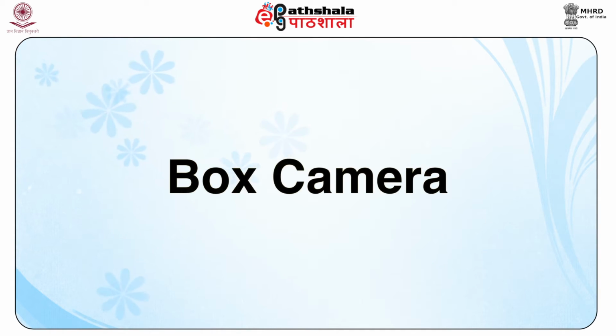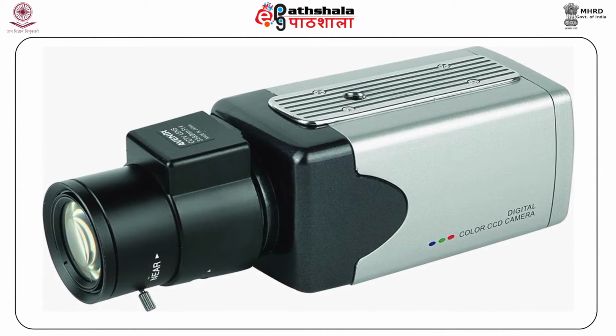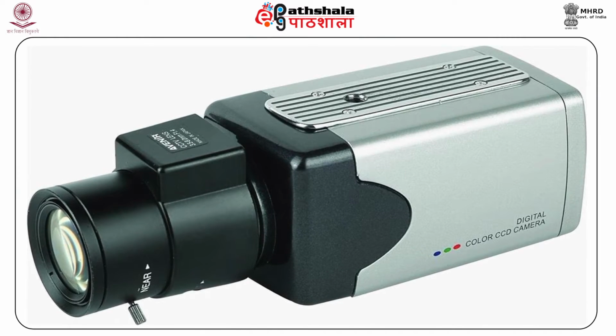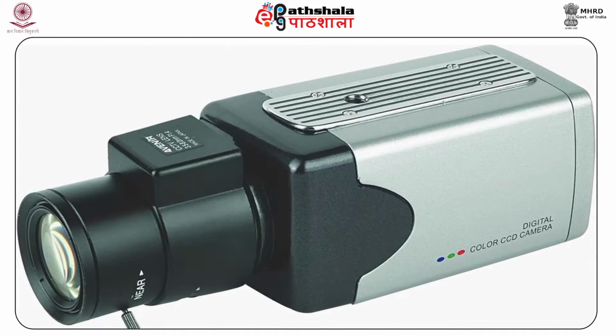Now second is the box camera. A fixed or box camera is the most common choice for video surveillance, as they feature an industry standard C or CS mount, which allows them to use a variety of lenses. This makes these cameras a fit choice for any video surveillance in commercial indoor environments. Enclosed in a weatherproof housing, they are frequently used outdoors too.